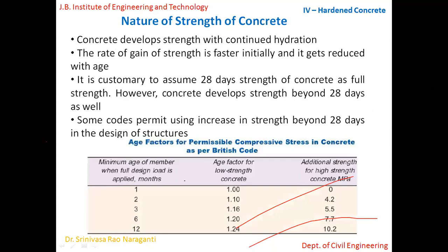Okay, now let's move to the third part of our discussion, guys. We talk about the nature of strength of concrete. We know the moment you add water to the concrete, hydration takes place. Then hydration continues. We'll talk about the curing part later. So basically, concrete gains strength with time. The more time you allow for the hydration to take place, the concrete continues to gain strength. That's what we're talking about, the nature of strength of concrete.